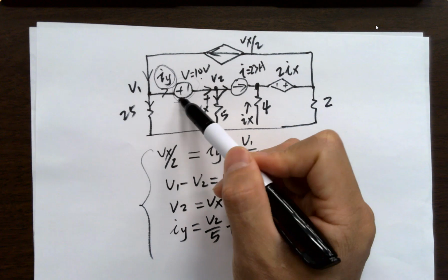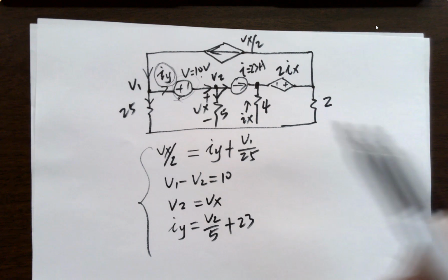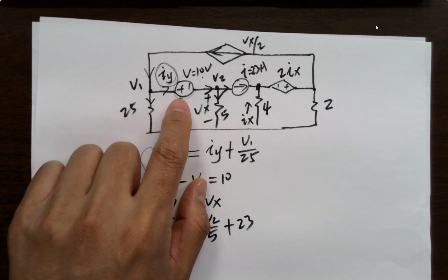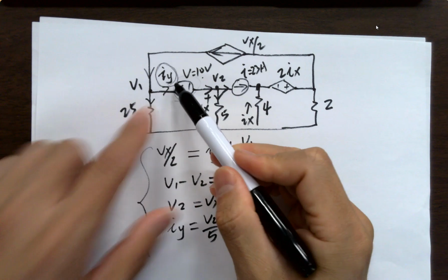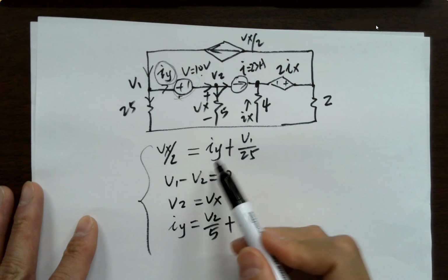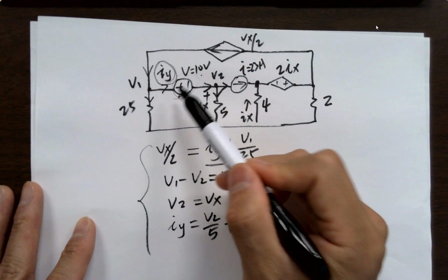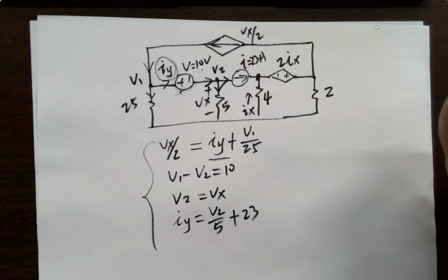It's flowing into it, so it's charging up the battery, so it's actually absorbing. If it's asking for the power developed by that 10 volts, or whatever voltage you have on your side, you have to add a minus sign in front of it. So you calculate this current over here, times the voltage, and add a minus sign in front of it. Okay, any questions on this? Good?